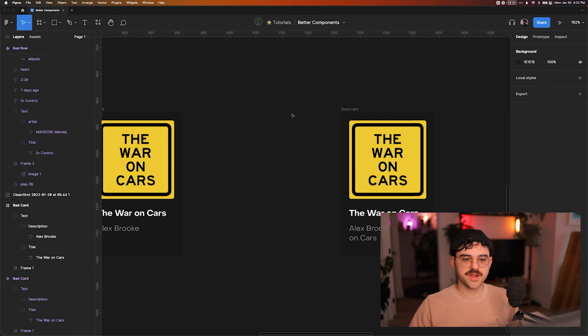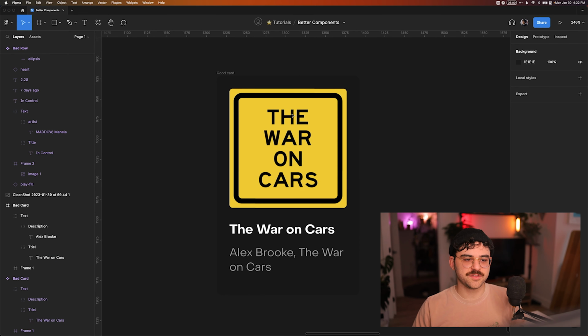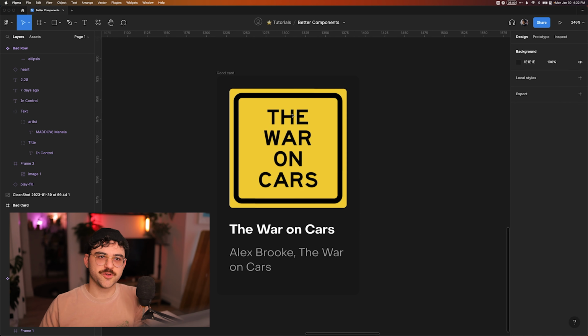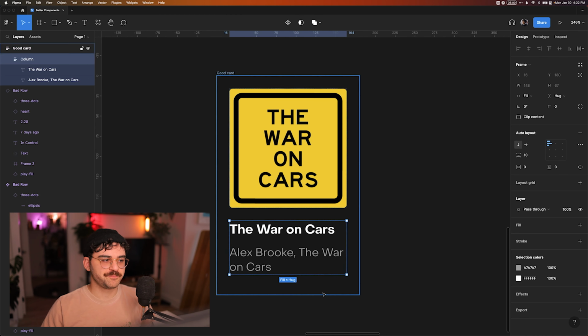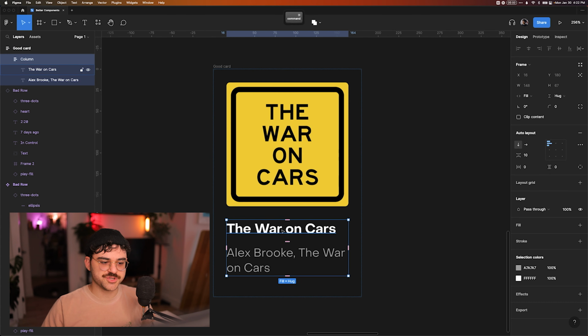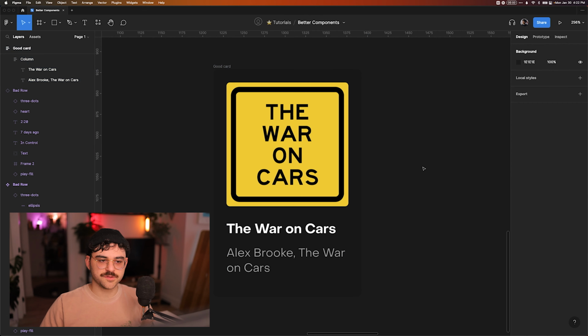So again, just try to be mindful of how you nest things, because when you put things into groups and those groups aren't doing anything, you're just making it a lot harder for somebody else to come in and understand how your component is set up. So be very mindful of that. You can see here a very simple take. We just have text. That text is in a frame, and this frame is doing something. The reason it exists is to lower this gap to 10 pixels. And then up here, we have a gap of 16 pixels.